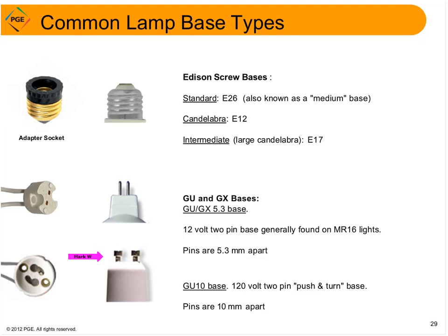So this illustrates again that you need to know what kind of lamp you're replacing so that you get the correct LED replacement. So it's really not that hard. You just have to do your homework and pay attention. So to summarize this section, LED directional replacement lamps and LED downlights are examples of great upgrade options that make sense right now and qualify for great Energy Trust incentives.